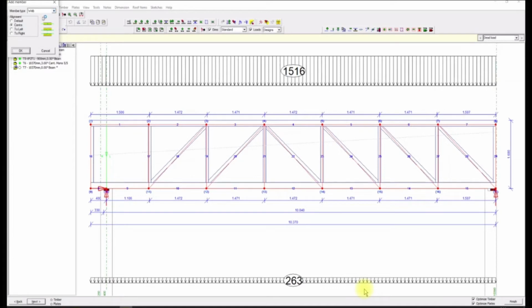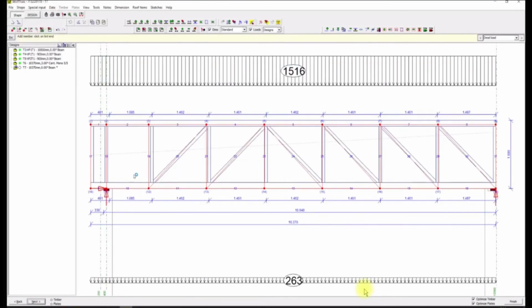If you keep it in center, it's on the center. And there's a possibility to change member type to scaling type, floor, anything you want. We can also change the member type, that is, what it is: top chord, bottom chord, diagonal or something else.